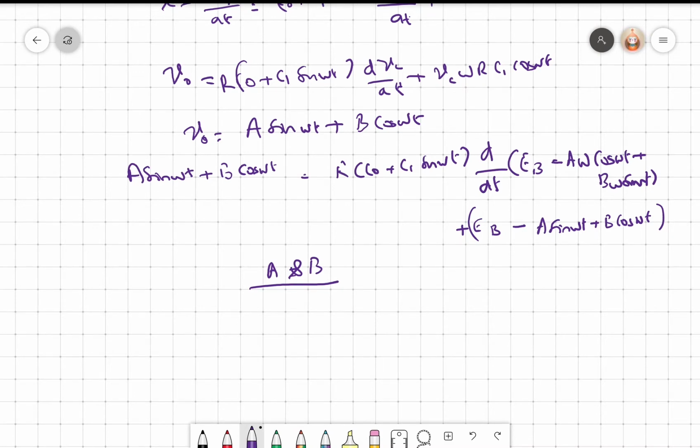The one way we can reduce the non-linearity is to make C naught much greater than C1. If you do that, obviously the non-linearity reduces. So what we normally do is, when we make the capacitor, we put for d a dielectric of constant epsilon r, and x is of course either in a fluid or in air with less epsilon r.